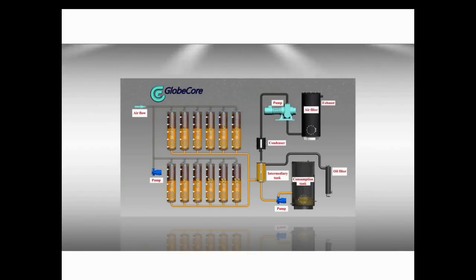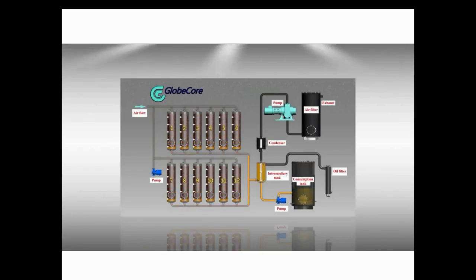Oil change does not allow for such a gradual acidity decrease. When doing a change, you can just flush and spray the transformer out, but after a couple of times, equilibrium comes and brings acidity to the new oil from the windings again.